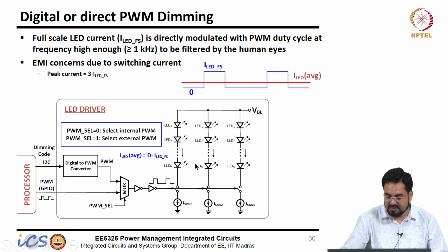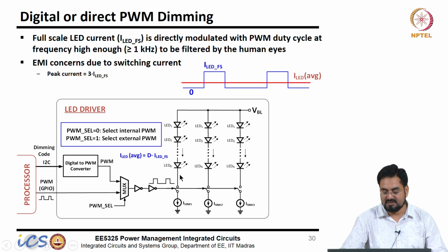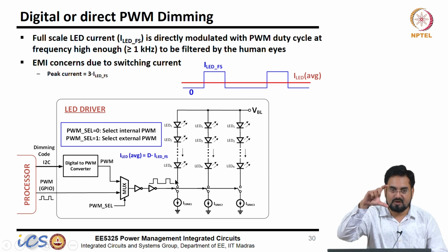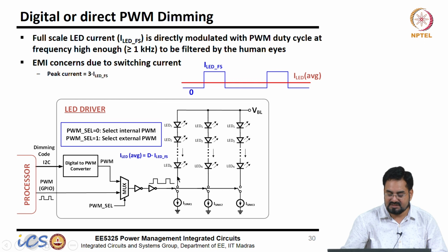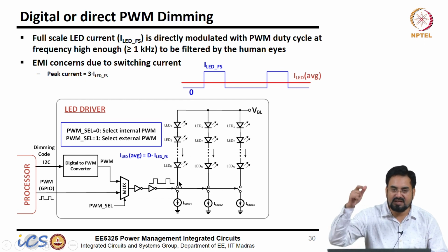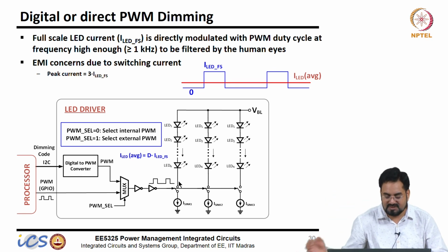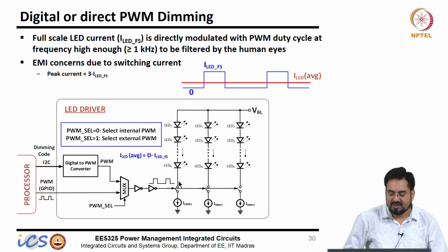The only thing is that your voltage will be changing, maybe changing a lot actually, especially this voltage. When it is turned on, we know there is a headroom voltage or dropout across that. When you turn off, it is quite possible it may go high. So it will be creating more like a switching voltage rather than a continuous voltage. So there are some EMI concerns with that, but it is usually taken care of by the design and layout. So, just like I said here, EMI concerns.